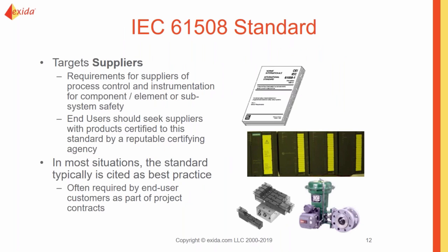IEC 61508 is that basic standard that was developed for really anyone that's using electrical, electronic, or programmable electronic devices in any products. Really should be following this standard. The way it's written, the tone of voice is really targeted to suppliers, those OEMs that are designing the components and subsystems going into the safety functions.